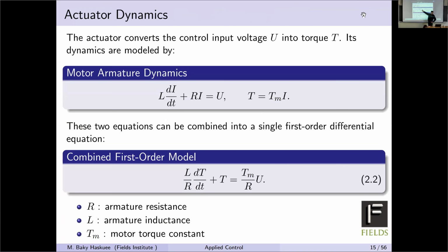So from here, what voltage do we need? What voltage we need depends on the T that we set constant. When we know Tm is constant, this map, given when you have the current, maps current to the torque of the motor. So this is the constant, for example. We want T to be 1, for example. We have this constant. What current should we have? Current determines, if you ignore the inductance, that Ri should be equal to U. R is the resistance of the armature. And I is derived from this equation, and then we know what voltage should be sent.